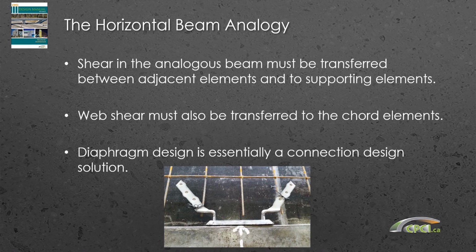Shear in that beam analogy must be transferred between adjacent elements to the supporting elements. Web shear, your shear flow, must be transferred to the chord elements. Because we're dealing with all these individual pieces and trying to tie them together to act as one big beam spanning from support to support, diaphragm design is essentially a connection design solution.